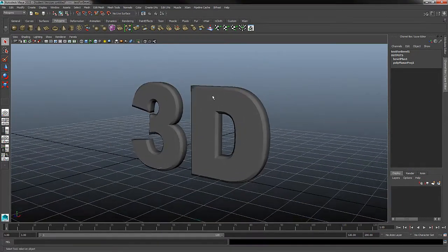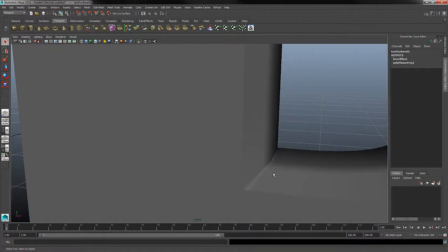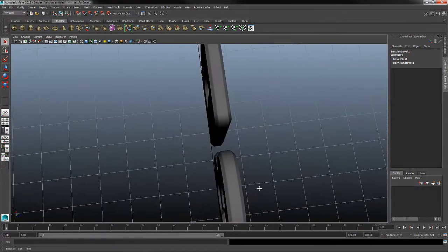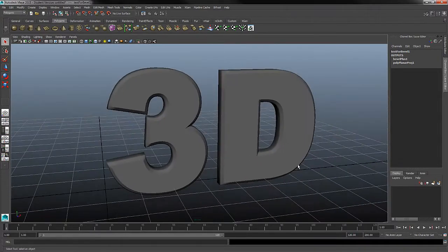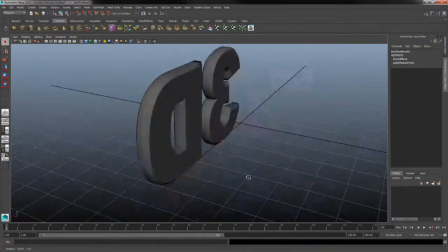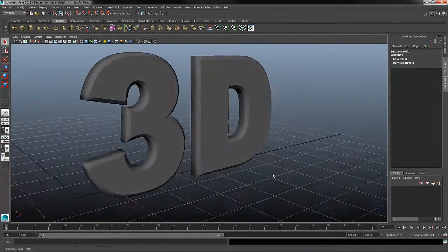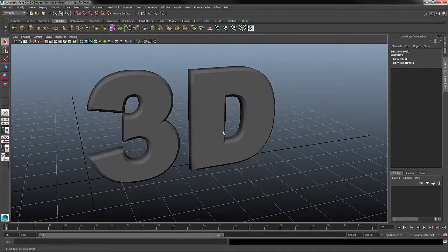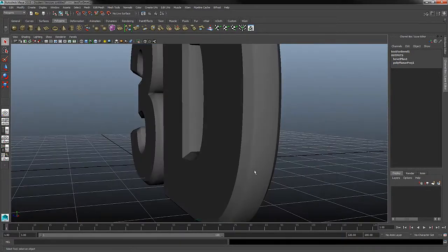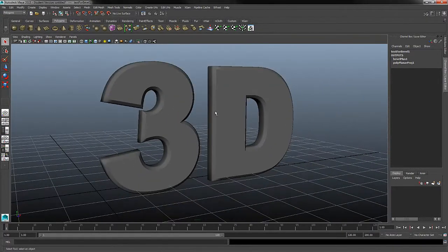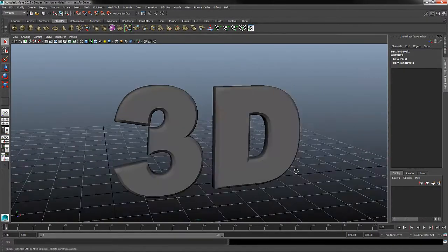Now using these 3 navigation types, we'll be able to zoom in to the little nooks and crannies of our logo, look at it from all angles, and investigate from all different sides. So it'd be good to practice using these hotkeys and becoming very comfortable orbiting 3D space. Again, a good tip here is just always hold down the Alt key when trying to navigate, and then you can switch between left mouse clicks, right mouse clicks, middle mouse clicks to be able to get into those little tight areas as you're investigating your 3D model.